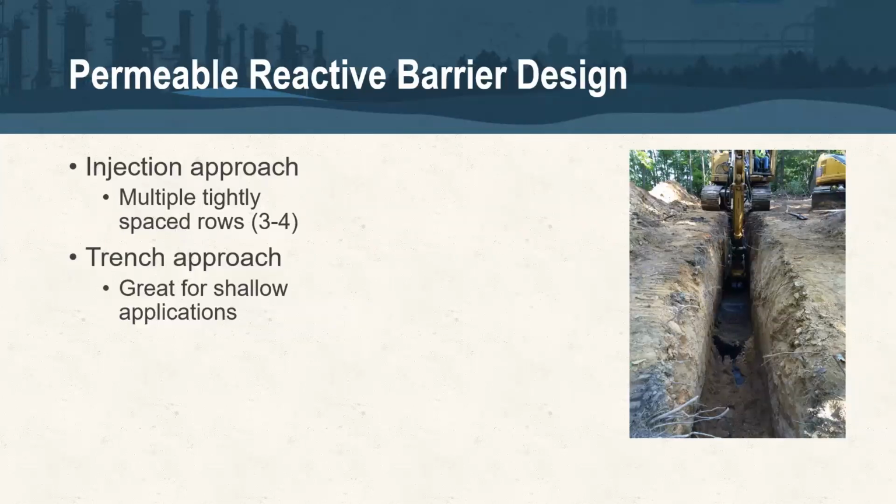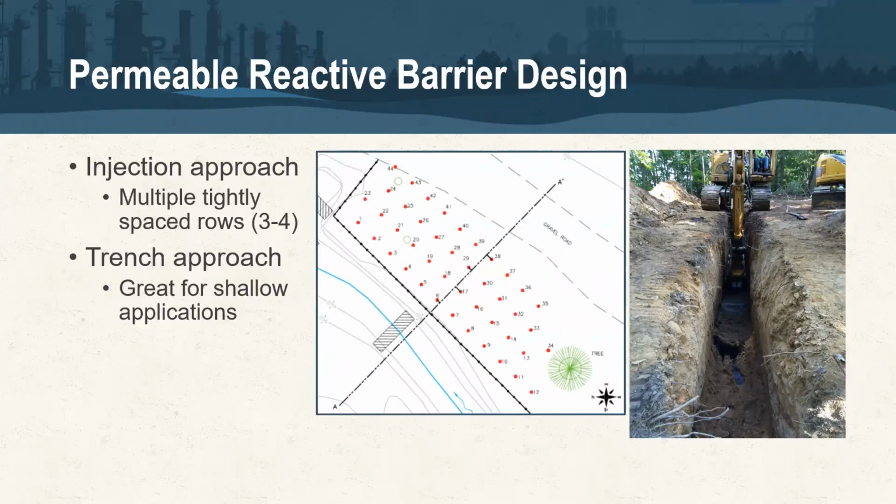We mentioned trenching. If you can do trenching for source area or PRB deployment, you should absolutely do it. But if you're on this webinar today, you're probably looking at in-situ installation. One of my comments here that's a global comment for installation of any slurry is with PRB designs, we see a lot of products, reactants, reagents being prescribed with a 1 or 2 row PRB, even products that don't create residency themselves.